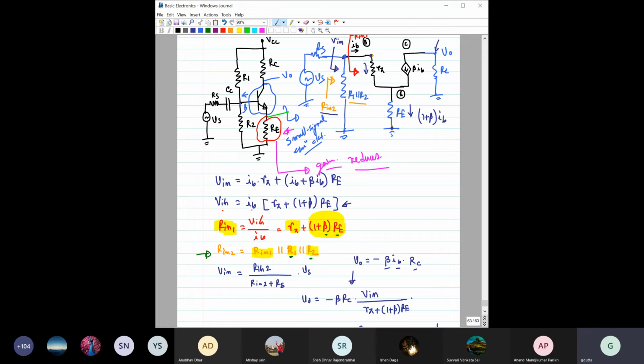So if we have suppose one capacitor connected in parallel with RE, then for DC this capacitor is open circuit. So for DC, RE will provide the stability, right? However, when you are considering the AC analysis, then due to this capacitance, this portion would be grounded, right?